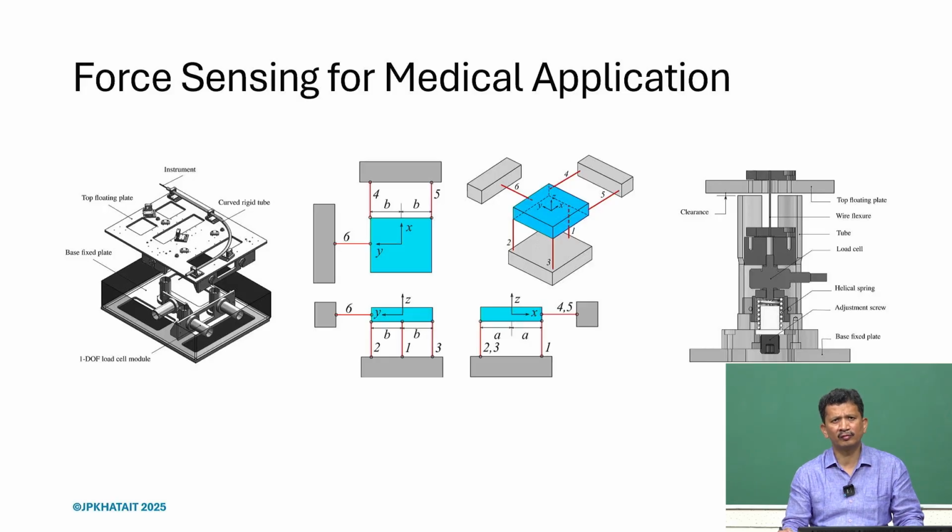deterministic. So what you see here in these designs, if you look closely, again we have used the 3-to-1 principle, which is used in machines and in metrology to constrain the system. Later we'll realize that these wire-like things we call wire flexures. For the time being, we can assume that it's supported along those lines only.